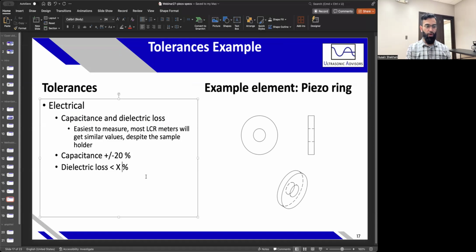So dielectric loss actually is related to the quality factor, and capacitance is very closely related to the charge coefficient. So in a way, you're getting really reliable measurements, slightly indirectly, because it's not the exact piezo components, but you are able to get a good handle on the dielectric loss and the capacitance. So if there are issues in measurement elsewhere, in the other resonant impedance measurements, you'll suffer less.